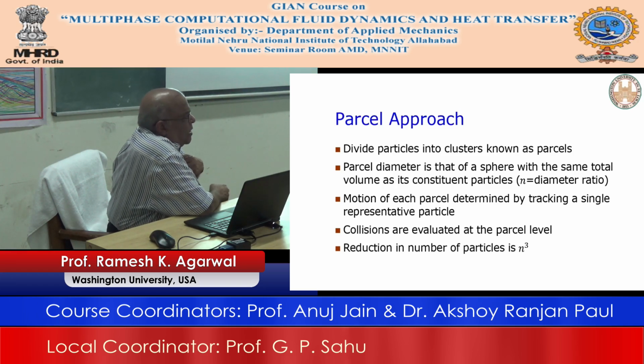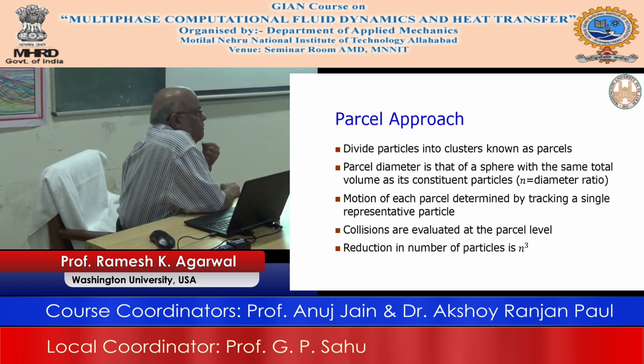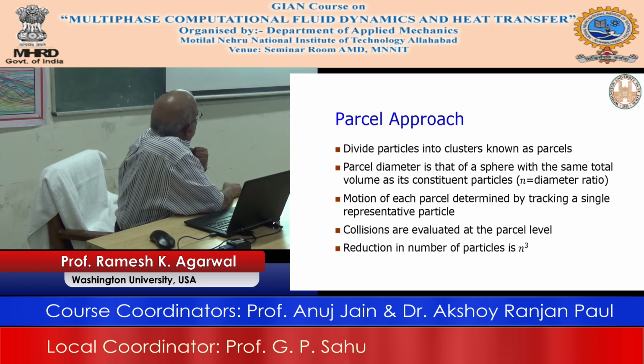Okay. So many times you have to make a judgment call about what is a good size of the particle, and then the motion of each parcel should be determined with a similar representation. And if you do this, then the collisions in the F term, the collision force, etc., and the drag force, you are treating them as everything identical.